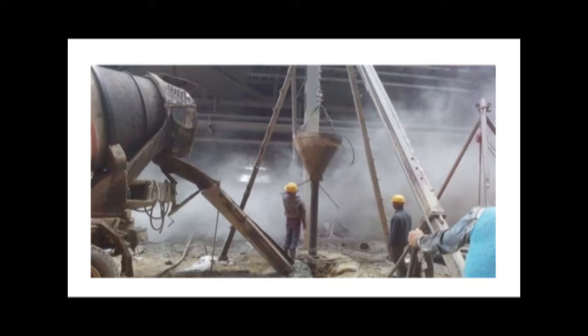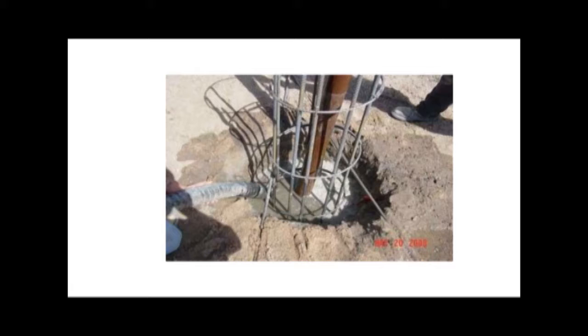After the reinforcement is revealed, it is drawn into the further structure. This reinforcement goes into the pile cap, and then the pile cap is drawn over it. So what is a tremie pipe, which is used for pouring the concrete? It is simply 2 meter pipes coupled together, provided with the hopper at the top. Once the concrete goes on filling this cavity of the pile, the upper couples are loosened and the pipe is removed, and the hopper is joined back till the concreting is finished.